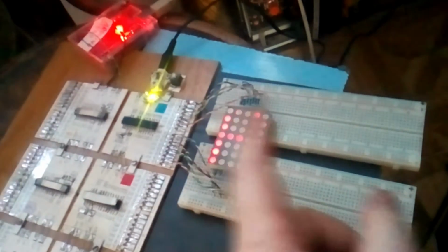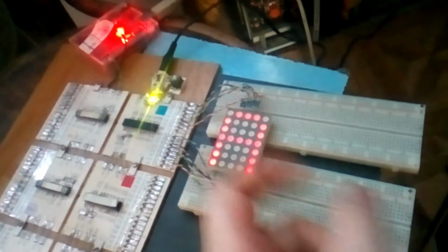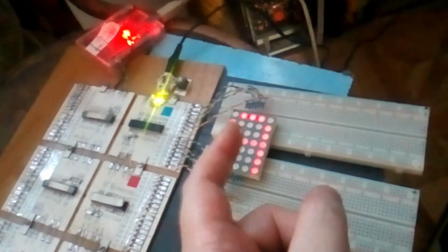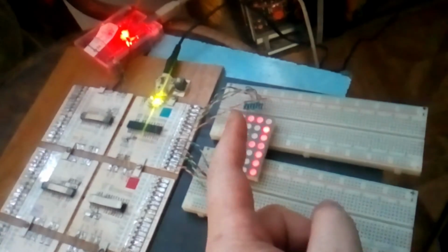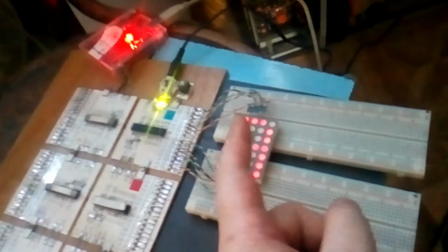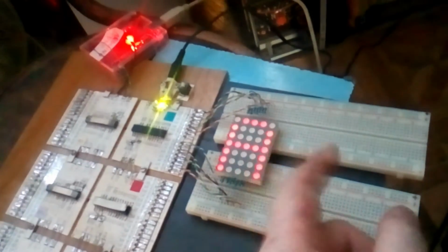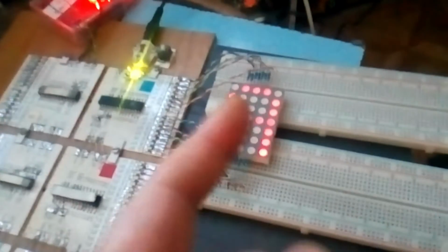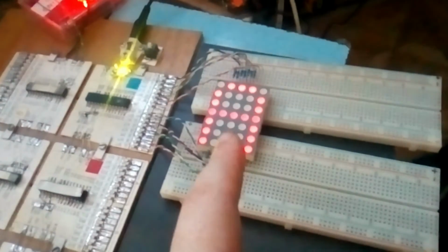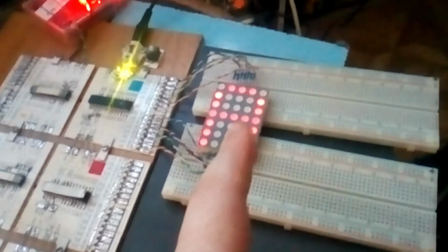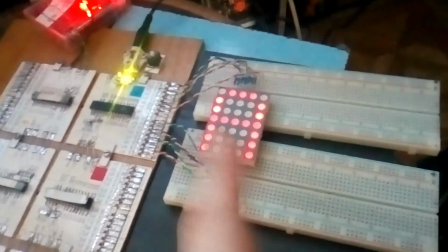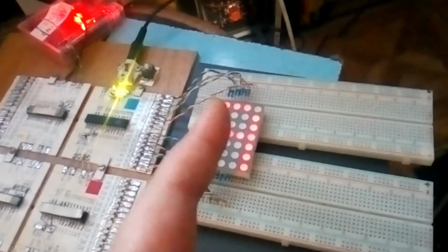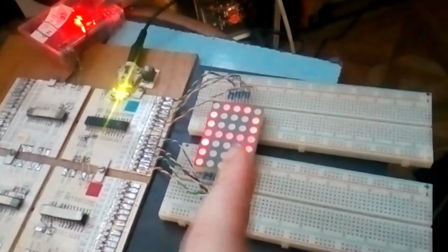I got results from other components with other pin numbers, linked in a different way, and they didn't include the resistors. I had to figure out by myself that because they are LEDs, they definitely need some resistors. I imagined maybe they already have a resistor internally, but I didn't want to risk it, and I put resistors anyway outside of them.